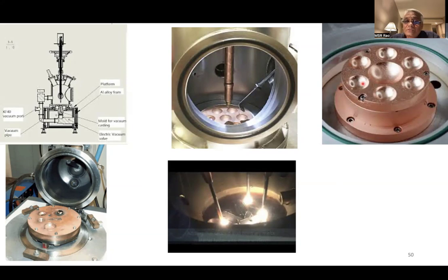So that means we need to do some calculations based on the atomic concentrations, atomic weights, and molar concentrations of these two elements. In most of the cases where the vapor pressures are different, you have to have one of the elements in excess of concentration, either in weight percent or atom percent. Otherwise, your final composition will not be the required one.